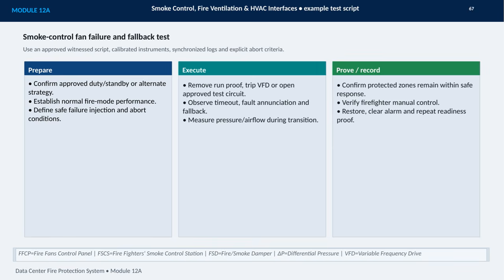Preparation comes first. I would confirm whether the approved strategy uses a duty and standby fan or another alternate arrangement, then establish normal fire mode performance. Before any failure is injected, the team must agree on safe test boundaries and clear abort conditions.